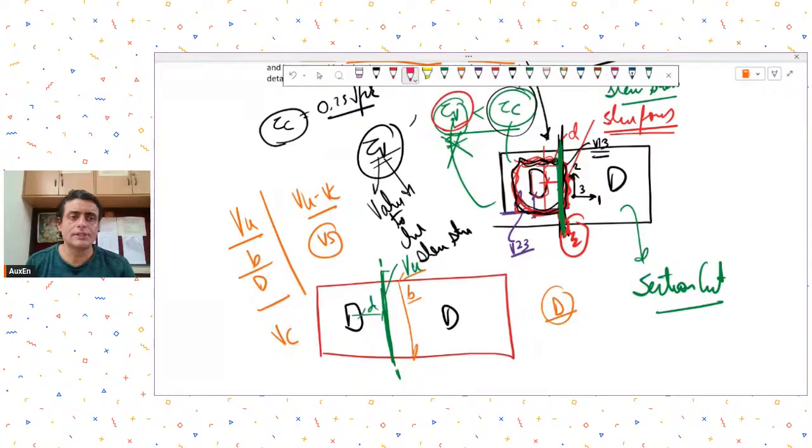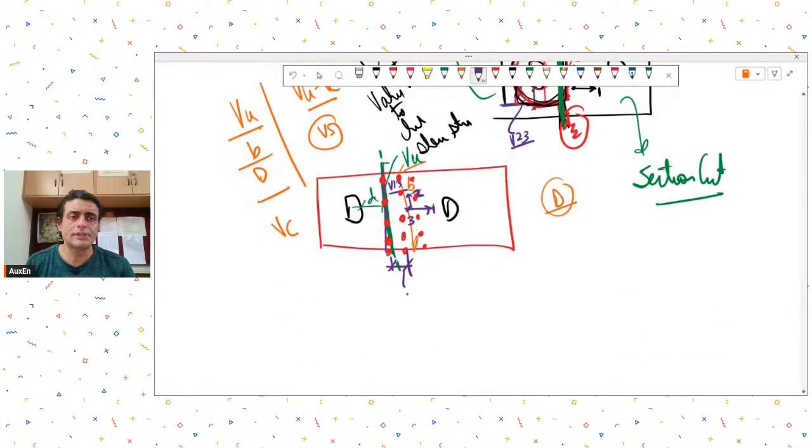Now if you are providing for a shear in a given direction, if I use ETABS or SAFE terminology, where 3 is out of plane, so if I have to provide for V13 shear, then your shear reinforcements will be placed like this. This will be your first set of bars, then at a spacing you will provide the next. This distance between these bars, these layers, will be your Sv, and the summation of all the reinforcement is your Asv. So this is how you will provide for V13.